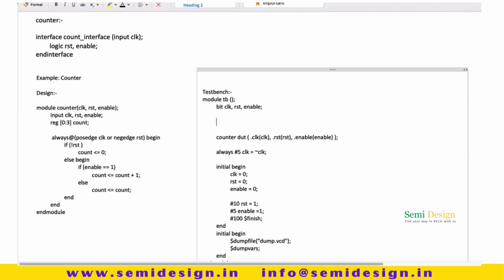How will we create it? It is similar to how we instantiate the design module in the test bench. First, write the name of the interface which we have given, counter_interface. Give it a name like intf, and declare the port in between the parentheses. Done. This is very simple, like declaring an instance in the test bench.